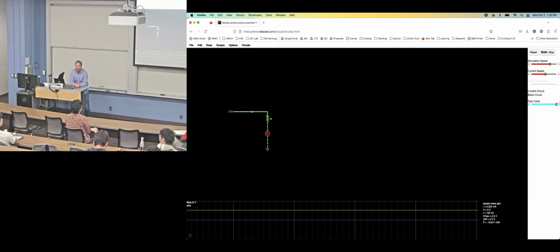Yes? Traditionally, for lights turning off and on quickly, is that because of alternating current? You mean like these lights right here? Yeah. These lights are flickering at 120 hertz because they are fluorescent bulbs, and there's a ballast in there that's going to rectify your 60 hertz. So now you get two 60 hertz humps giving you 120 hertz, and that's how fast those lights are flickering. It's not what you asked, probably, but that's why I got excited about telling you.